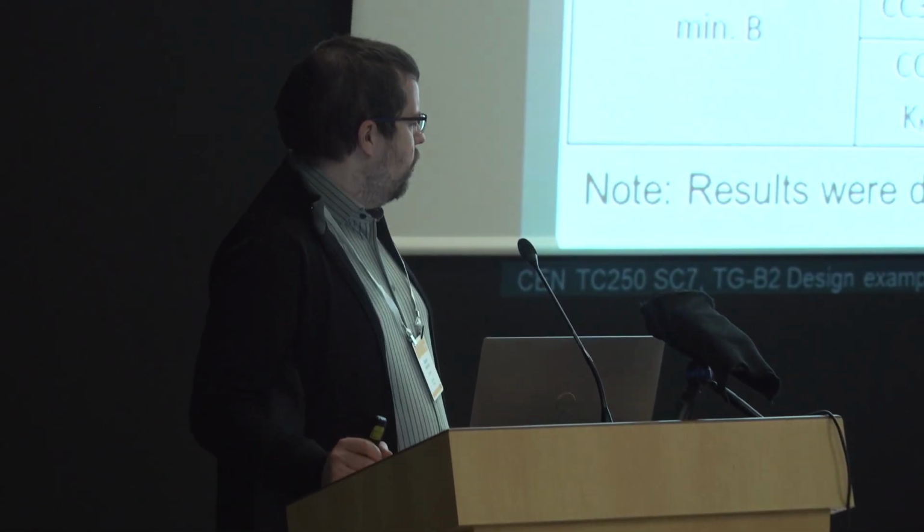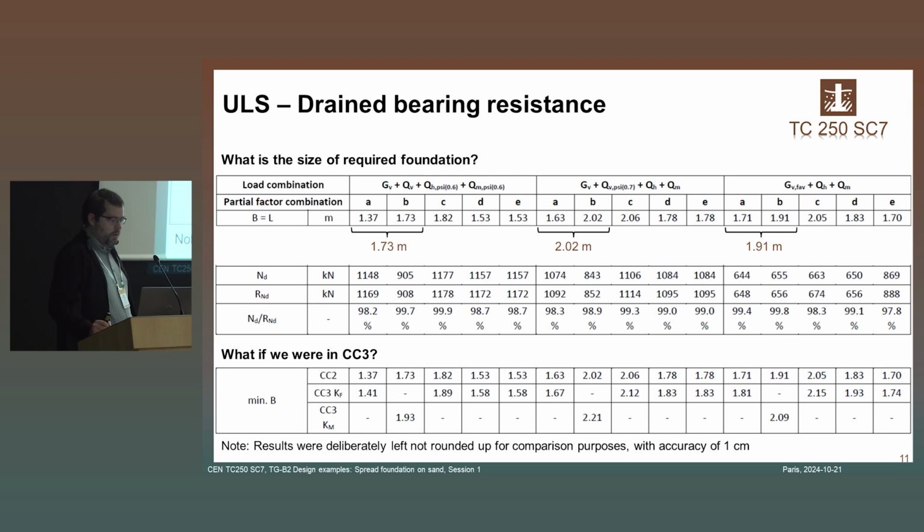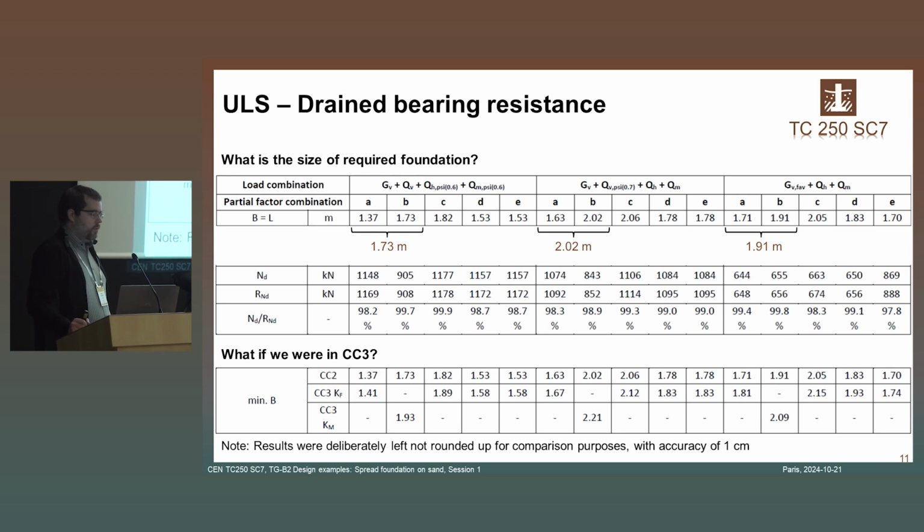The one particular case is the verification case C that I think it's specified. I don't remember now the whole phrasing, but it's specified that we should put the partial factor on the actions. Yeah. We never combine or choose which one we want to do. Theoretically, there is an opening for putting it on resistance, but it's more theoretical because for spread foundation it is not used, and as far as I know, none of the geotechnical structures actually allows for putting it there. I think it's something that comes from EN 1990, if I'm not mistaken.